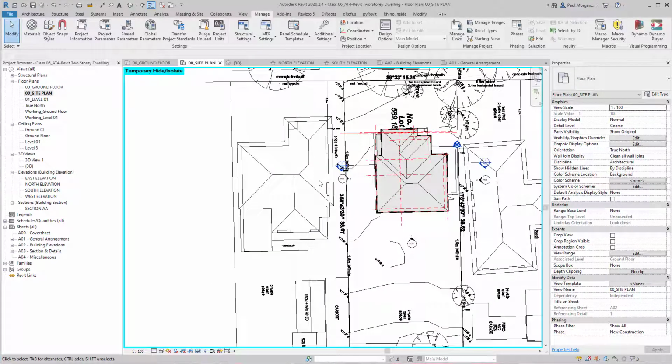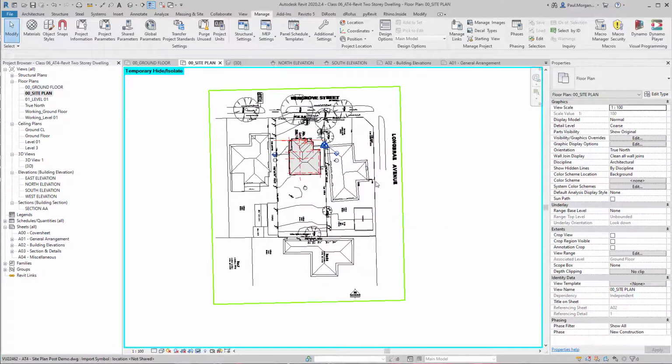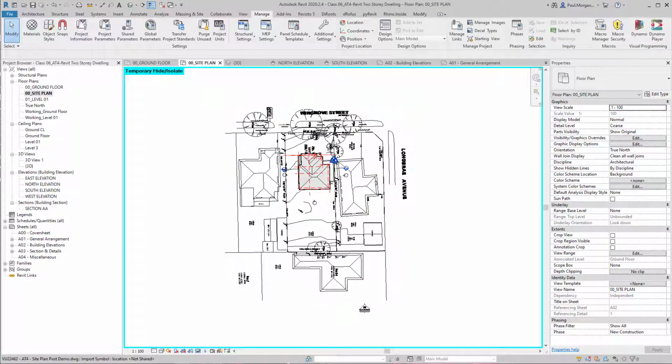Okay, and you can see that's updated now and the CAD file is back in its original position. So it's not optimal, but this is because we were relocating and rotating the project, changing its levels after we had built. If you refer back to class 1, I said it's not good habit to do that. You can't avoid it.